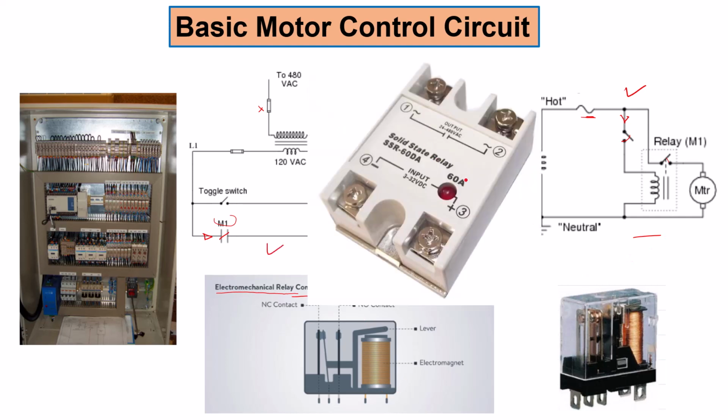Now, just a note on solid state relays versus electromechanical relays. Basically, the first choice is to go for electromechanical relays. Why? Because they are cheap, and that means if one is broken, you can replace it quite easily. That is in contrast with your solid state relay, which is made of electronic circuitry inside and is expensive, right?